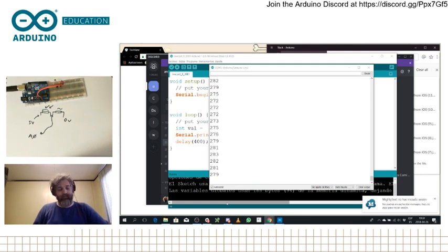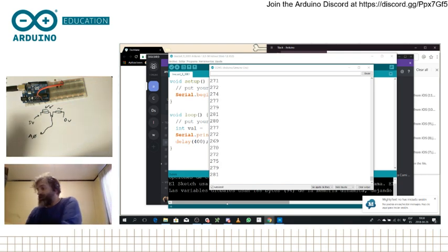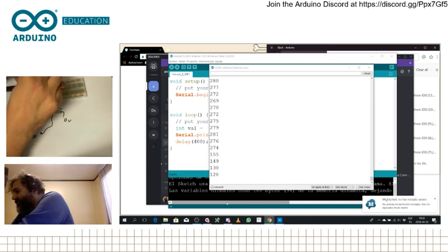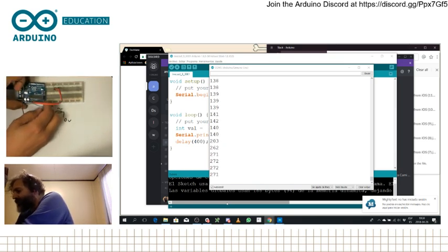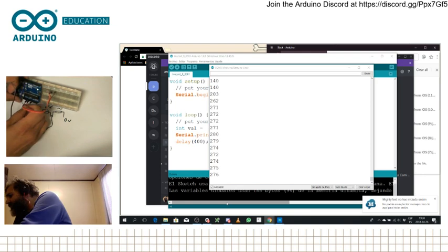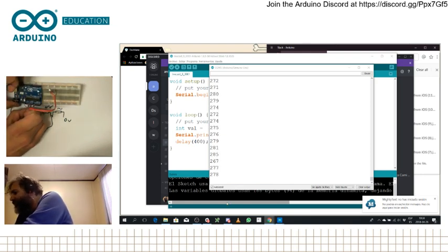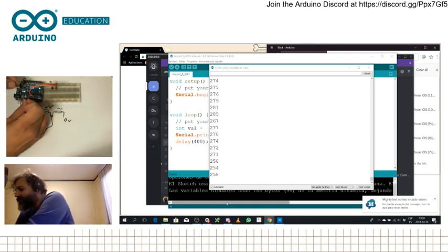I have no idea, again, because I took it from a box in the lab and it probably has been used for other things. So I'm going to try to power it using a small trick. I will just punch together a pin with the actual connector on the board and see if I can get it to work. I'm going to first plug in ground, and then I will plug in 3.3 volts. Because these lasers either work at 3.3 volts or exactly at 5. And if they work at 5, I have to do some more work.